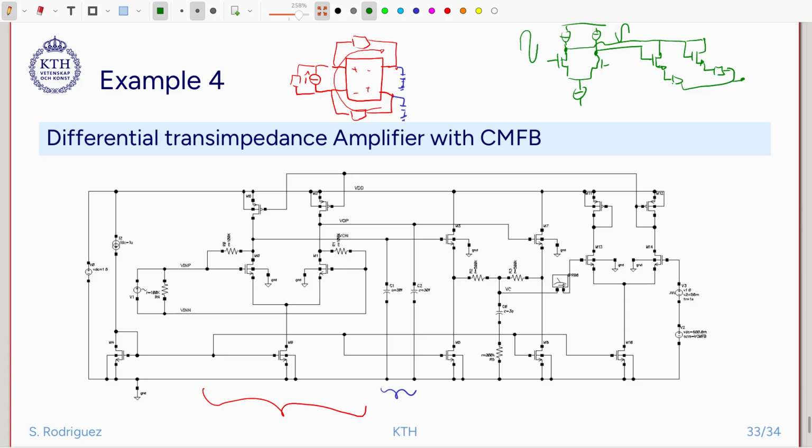In this case, it is already DC. We can already use it as it is, but very often we put another capacitor here. And the reason for that is that we might want to have a very well-defined pole here, typically a dominant pole close to DC. So large resistors here, and with a capacitor, they will place a dominant pole.